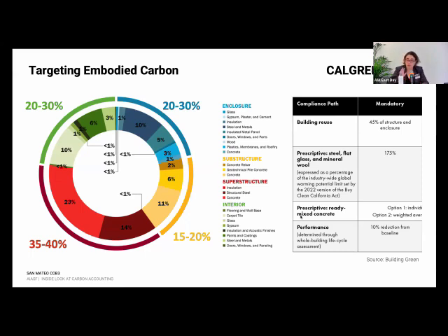For the architects in the room and online, we have 20 to 30% in enclosure. And I think that's us as an industry. We need to keep doing better on that. We have aluminum that's high in embodied carbon. Also glass. It was great to see that glass is in Cal Green. Let's keep partnering with our manufacturers to ask the right questions and continue to drive low carbon products to the market. For the interior side, you're also carrying 20 to 30%. Watch your service life. How often are things going to be replaced within your building, and thinking through the value of the carbon that you're putting in from there. So just want to make sure you're aware of the hotspots and that you're not going to necessarily go and reduce everything, reduce it where you're going to have the most impact.